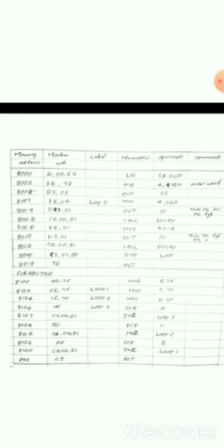The process of alternately sending 0F and F0 through port C, with the delay subroutine in between, is repeated. The port addresses are: for port A the address is 00, for port B the address is 01, for port C it is 02, and for the control word register the address is 03.